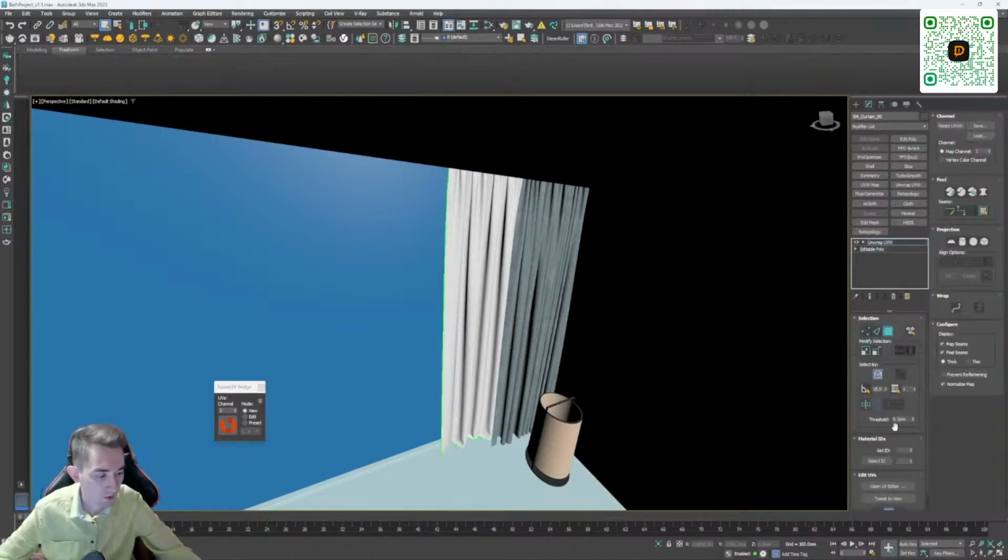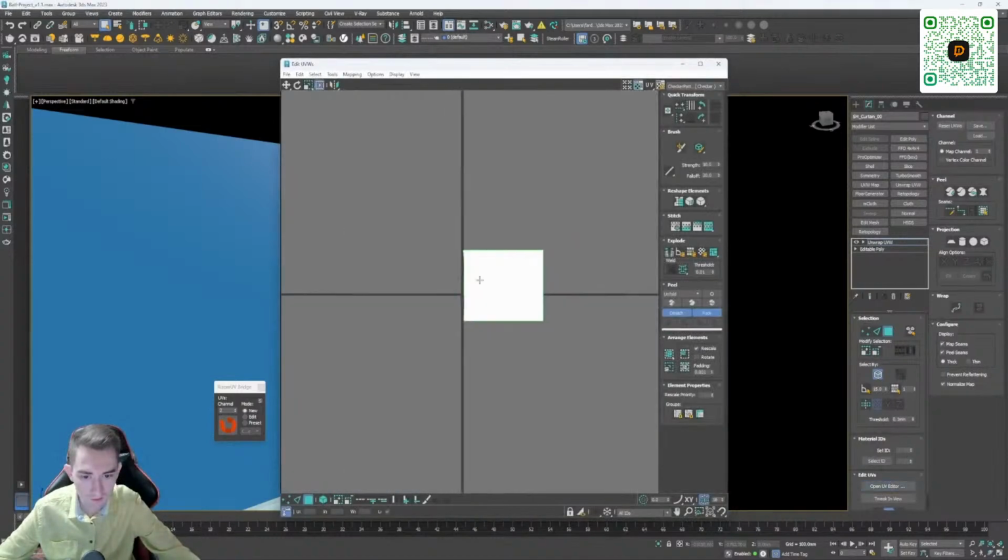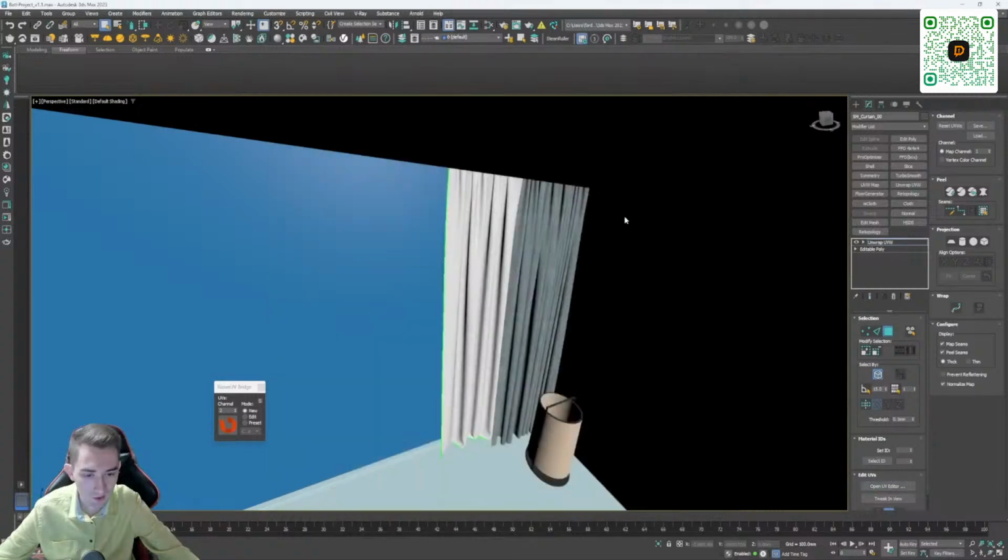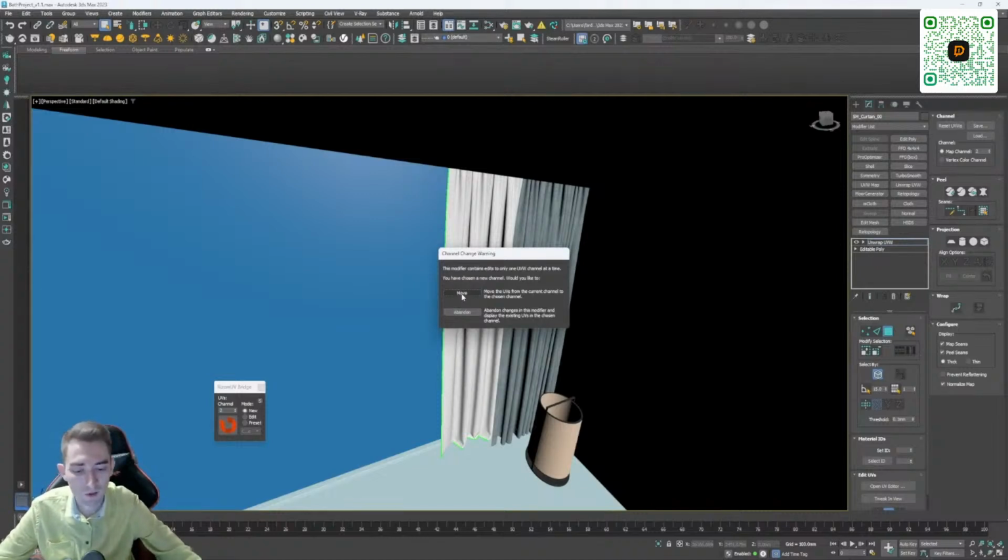In this modifier, we usually look at Open UV, and here in principle, we can see the scan. Well, it's not always obvious to see it. Sometimes you can just check, transfer the scan, that is, select Map Channel to here and click OK. A copy will be made from the first channel to the second channel.